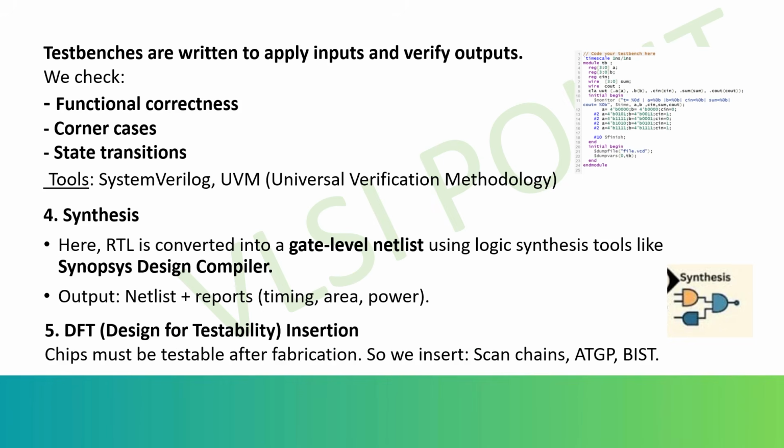Then DFT insertion will be there. So after synthesis, we make the design testable so that we can check each manufactured chip for defects. Common techniques are scan chains, which allow reading and writing of internal flip-flops during testing. Then BIST, that is built-in self-test, so it automatically tests the memories or logic blocks.